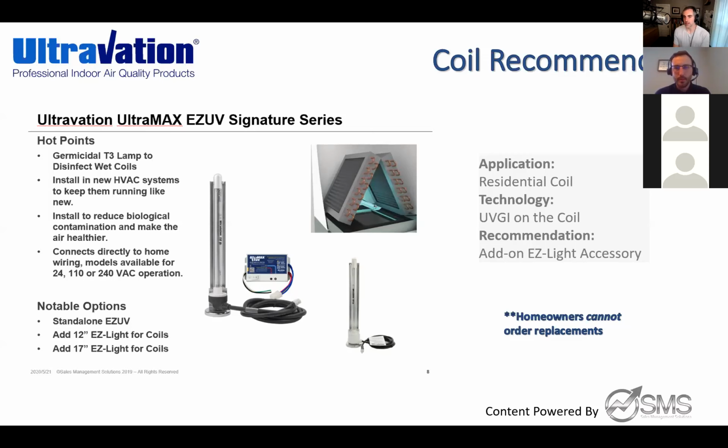Plus, from an install standpoint, I just have to go down there. Again, this should be done by your contractor, but I do it myself. I just turn the power off and pop the rubber power boots off. There are two screws holding the bulbs in. I take the screws, pull the entire lamps out, get rid of them, put the new ones in, pop the power boots back on, flip the power back on, and I'm done.